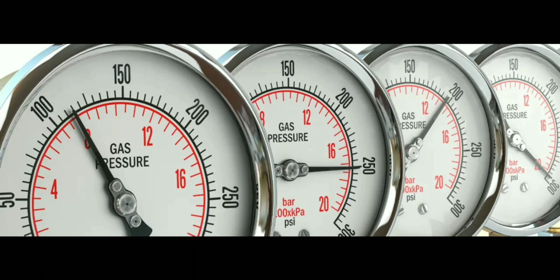An absolute pressure transmitter commonly measures pressure in units like Pascal or Torr, but a gauge pressure transmitter often measures pressure in units like pounds per square inch, which is PSI, or bar. Understanding the distinction between absolute and gauge pressure transmitters is crucial in selecting an appropriate device for a specific application, considering whether the reference point should be atmospheric pressure or absolute vacuum.